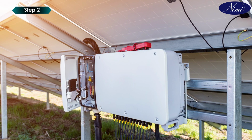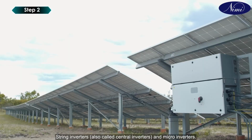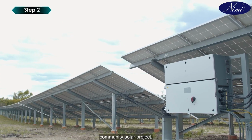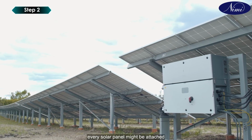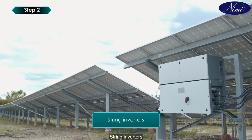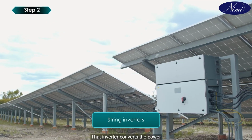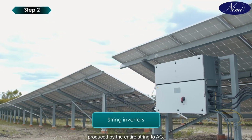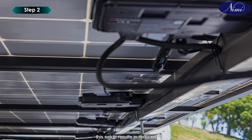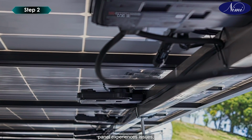There are two main types of inverters: string inverters and micro inverters. In a large-scale utility plant or mid-scale community solar project, every solar panel might be attached to a single central inverter. String inverters connect a set of panels, a string, to one inverter. That inverter converts the power produced by the entire string to AC. Although cost-effective, this setup results in reduced power production on the string if any individual panel experiences issues such as